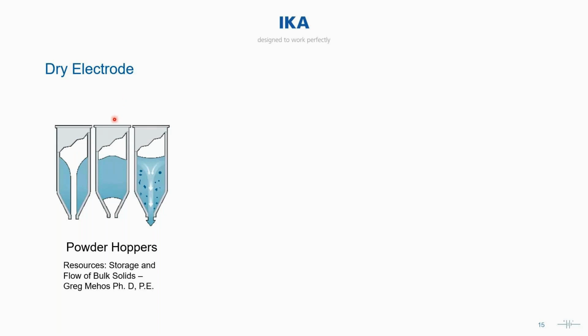We then see this middle hopper showing us an example of a bridging concern. This can again happen from an incorrectly sized hopper, not taking into account your specific powder properties, where you can actually form a bridge at your outlet and not get any flow out of this hopper, even though you would look at it and think that it is full.